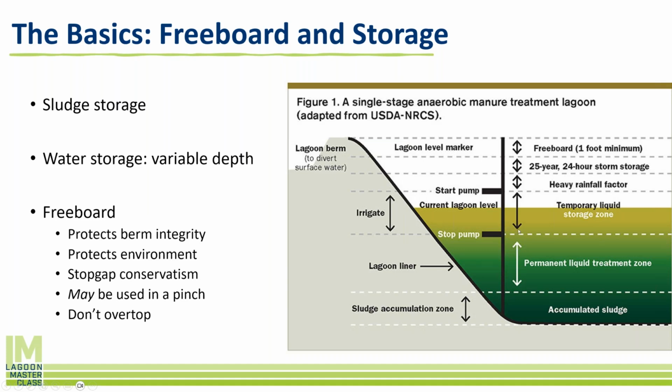Maybe they want to operate it differently. Maybe this accepts fluctuations in flow from the town. Could be the 8 a.m. shower time period brings lots of water, but in the middle of the night the water level slowly trickles down as there's less inflow into the lagoon system. Most lagoons don't have that variability, but engineers do design in, on occasion, some level of variability to a lagoon side profile. And then what we have after that is what we call freeboard.